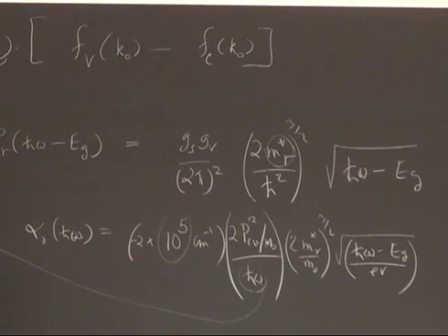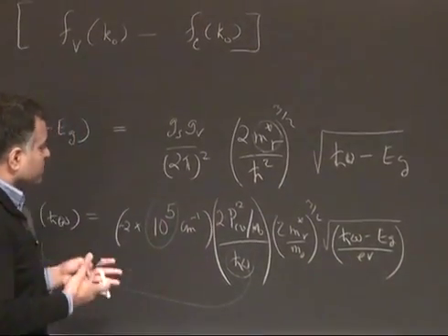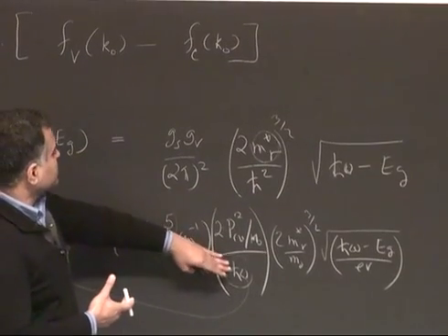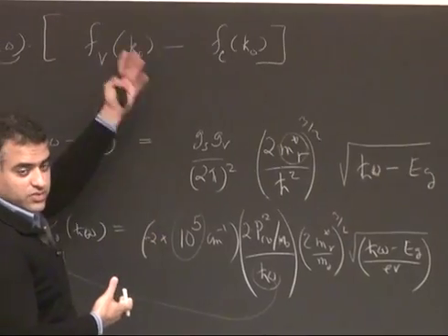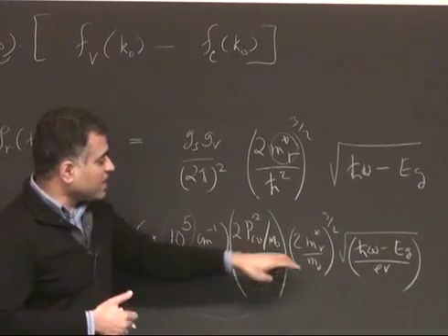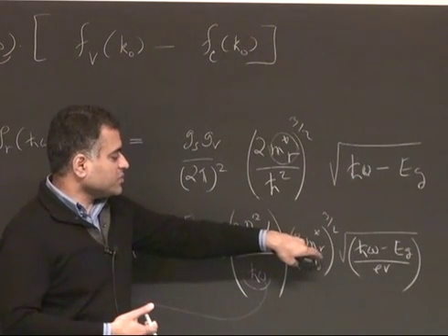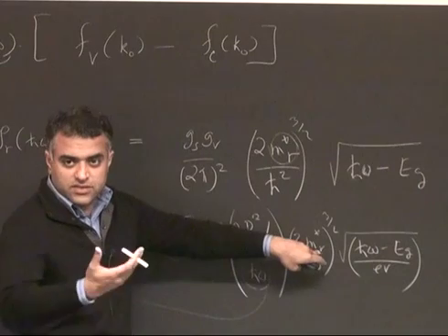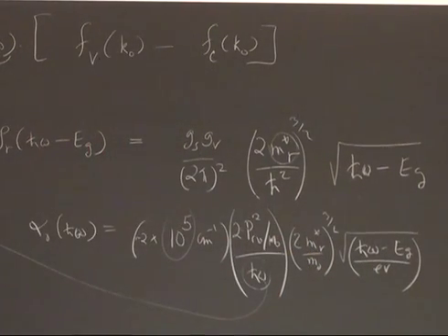And the other thing is, clearly, if you can increase the oscillator strength, you can absorb stronger. And the nice thing is, if you can absorb stronger, we'll see you can also emit stronger. So it's a reciprocal behavior. And the larger the reduced mass, the larger this property. So higher density of states will allow for more light emission and more light absorption as well.